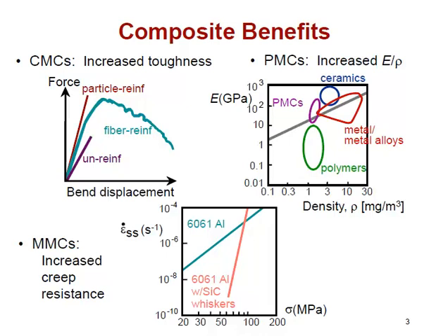And so you've got a modulus in and around 0.01 to 1 gigapascals and a density of right around water, a little over 1 megagram per cubic meter. And as we move over, as we add some reinforcers, particulate, fiber, and different types, we could add other polymers like carbon fiber, we can add ceramics, we can add metal wires or metal fibers.